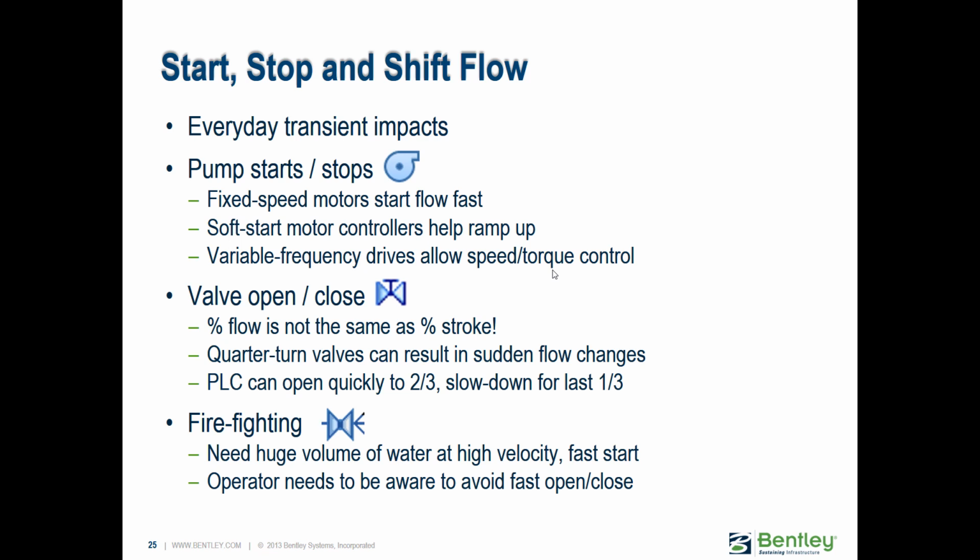Firefighting usually needs quite a large volume of water at a high velocity when that occurs. So what you have here is sort of the opposite of a valve closing. You have a sudden valve opening, basically, and there can be a transient as a result of that, a downsurge that occurs. So the operators need to be very careful not to open or close those valves